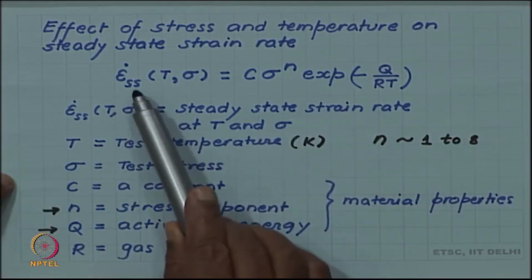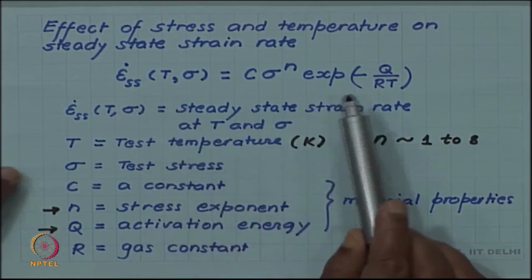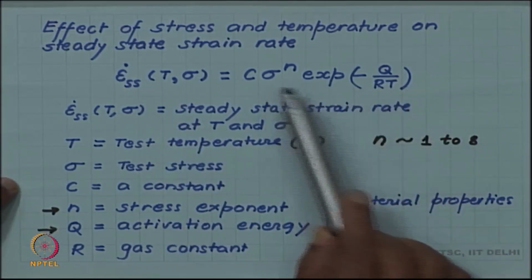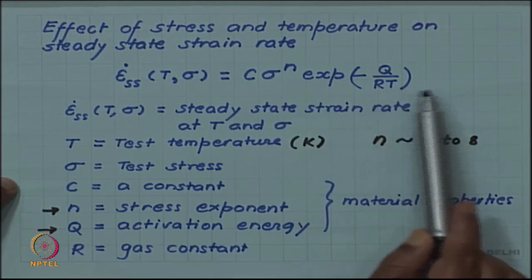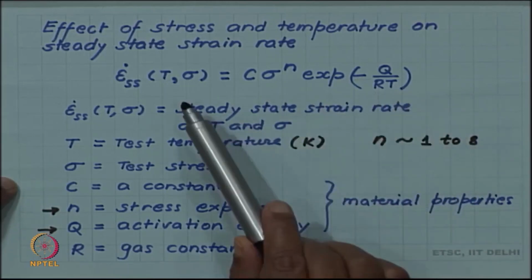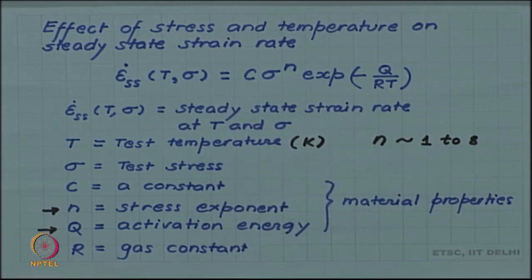So, the steady state creep rate is a strong function both of stress and temperature. A slight increase in stress and a slight increase in temperature can significantly enhance the steady state creep rate, and thus dramatically can reduce the creep life. So, creep is a very stress and temperature sensitive process.